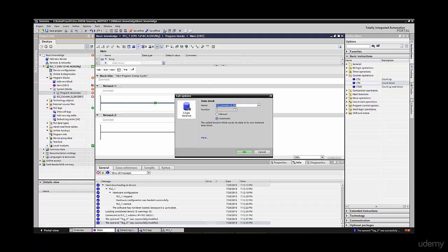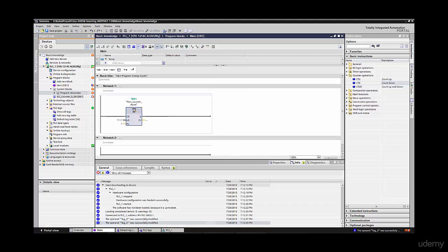Data block, so the name of our counter, for example first counter down, because it will subtract the value by 1. As you see, it can be a counter of many variable types. We use the integer. We have to put here the conditions which will count down this value.